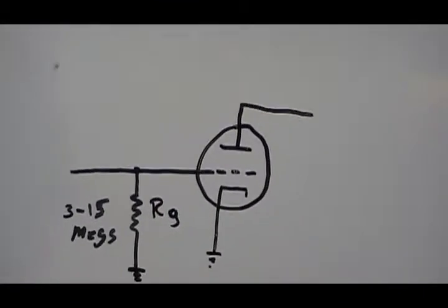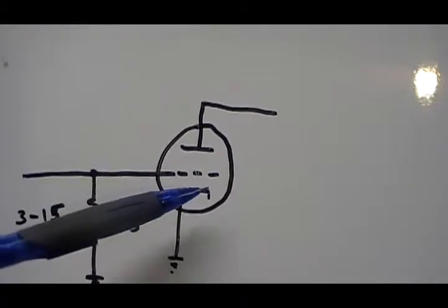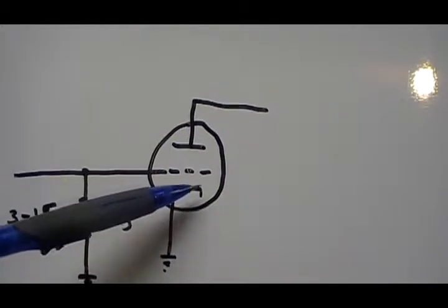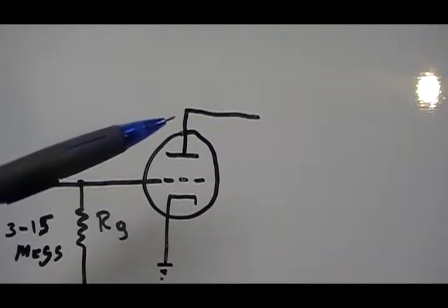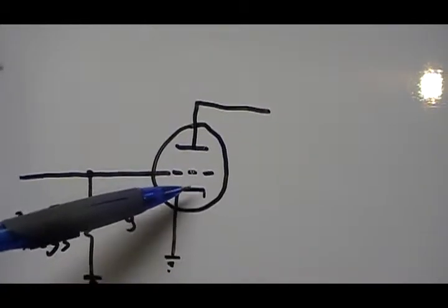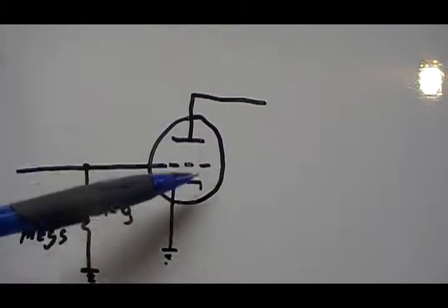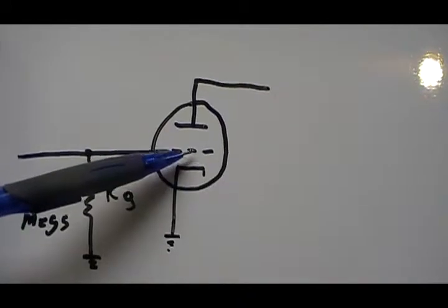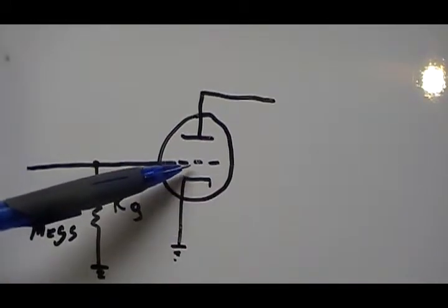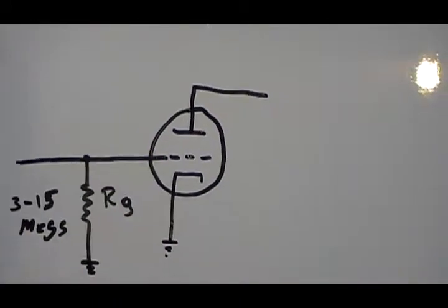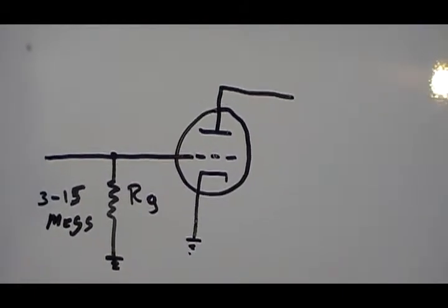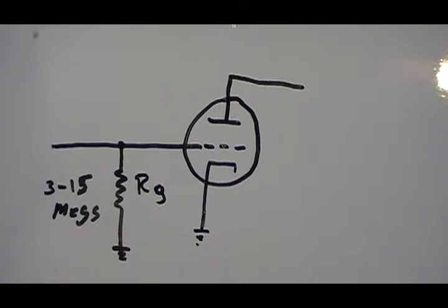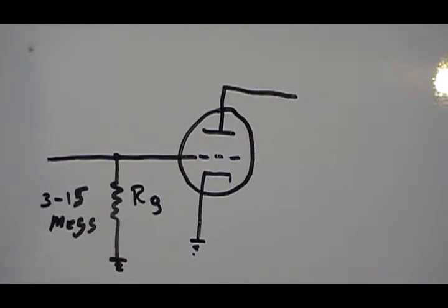And why they do that is, what contact bias is, the cathode is a negative potential in the tube. So while it's got all these electrons flowing through, some of these electrons are going to make contact with the grid, and they're going to stay there. And that ends up making the grid look negative with respect to the cathode and everything else.